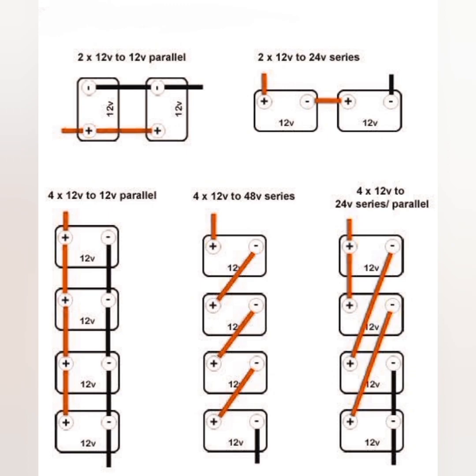For example, if we say each single battery has 10 ampere hour, then automatically if we connect them in a series parallel combination, it will increase to 40 ampere hour at 24 volt battery. In the next slide we will have a deep view on the calculation of these battery combinations.